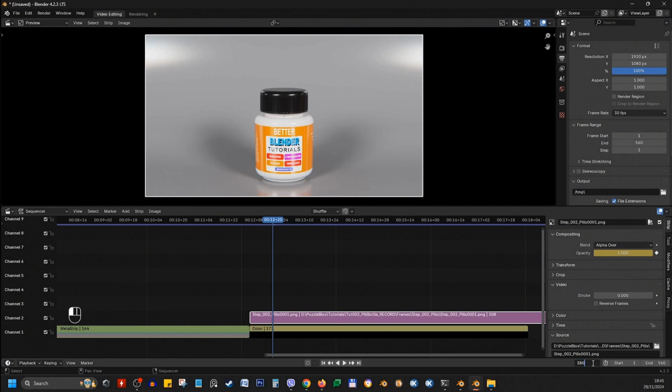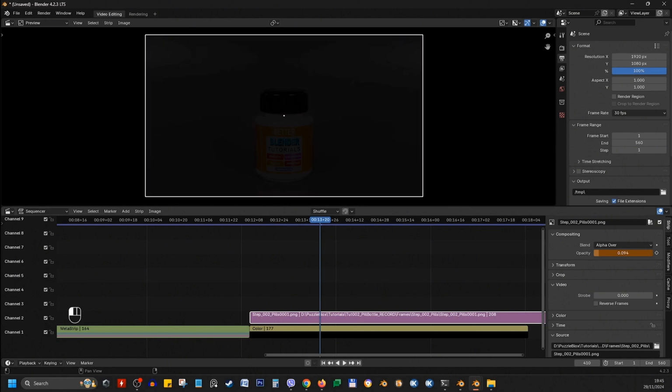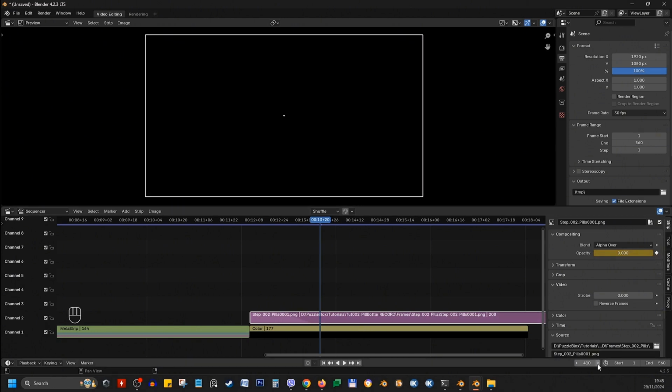Go to frame 410. Wherever we write numbers in Blender, we can just add a certain amount. So here next to 380, just write plus 30, and that's 410. Enter. Bring the opacity to 0, add a keyframe, and now we have a nice fade out to black at the end. You can hover your mouse above this 410, hit Ctrl C, just while hovering, you don't have to click, and then hover above, end, and Ctrl V. This will paste the number. So the end frame is 410.